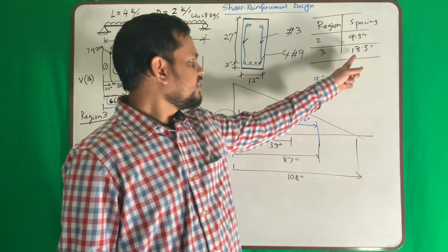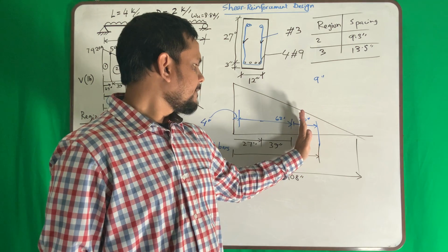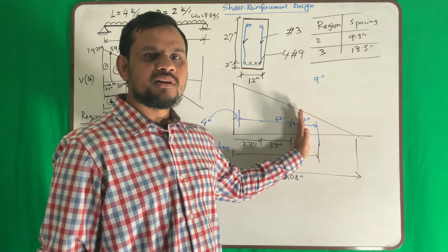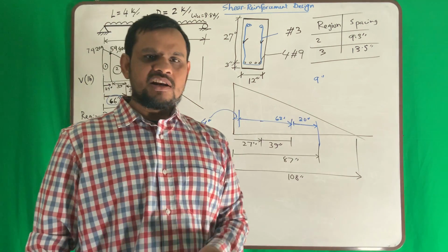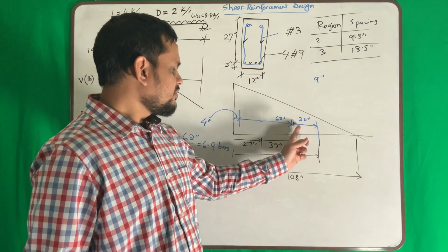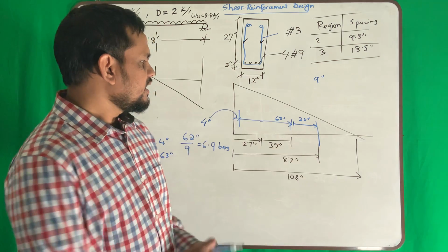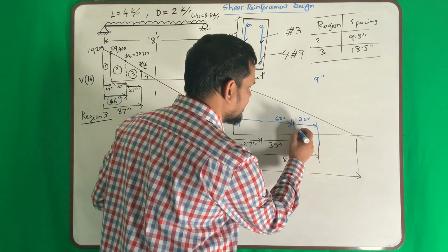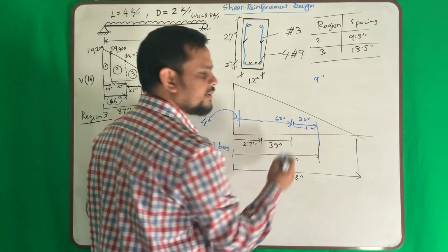If you provide only 13 inch, you can provide only 1 bar. But it's a matter of only 1 bar or 2 bar. So better to be safe, and you have 21 inch, and if you provide only 1 bar after 13 inch, then something is left here.